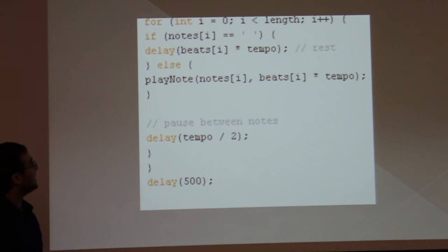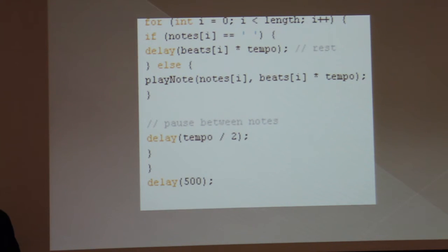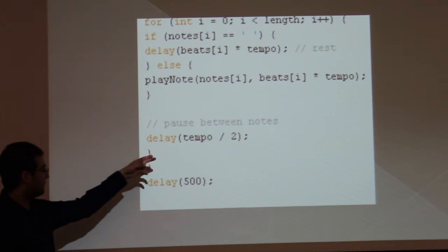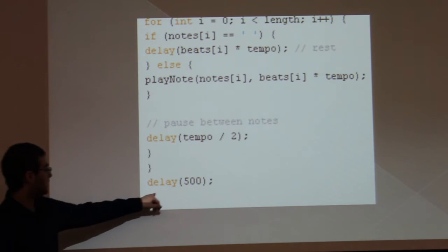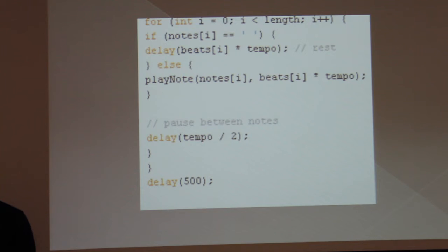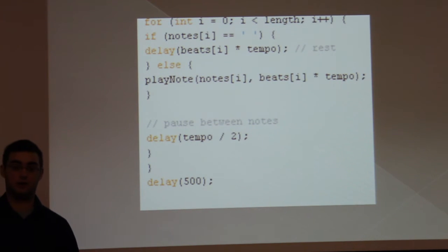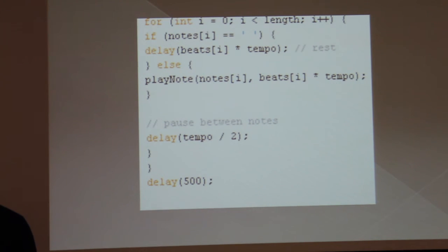So this is if the light value is a certain value, and I have it set up at 600. What it'll do is play the melody that I have set up, which is the melody of Hot Cross Buns. And again, this is the tempo, and then this is the end of the loop with a delay of half a second in order for the whole program to restart, and then it'll take the temperature again, and it'll see if the light value is over 600, and if so, it'll play the melody again, and if not, then it'll just keep going through forever and ever.